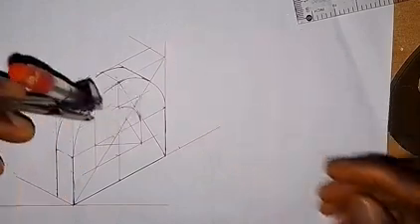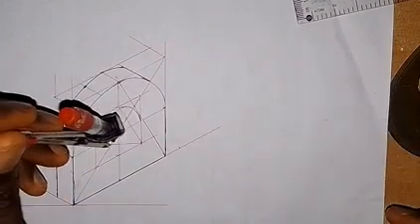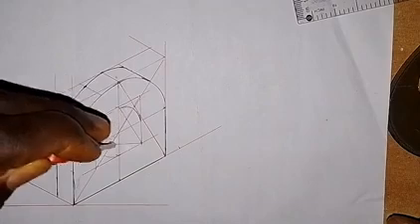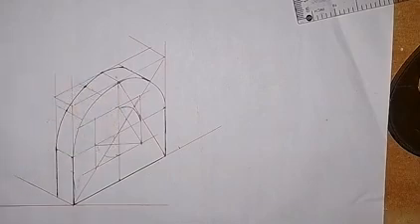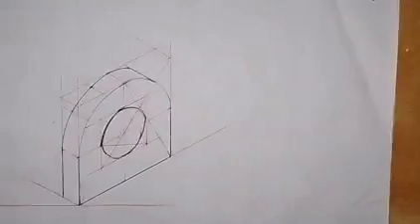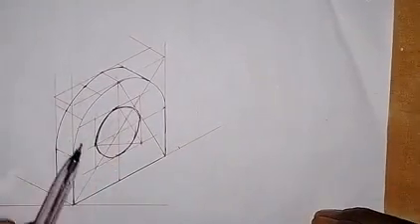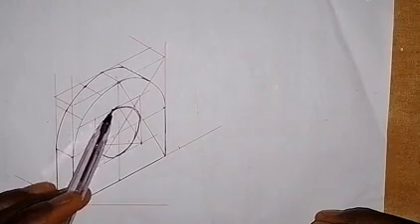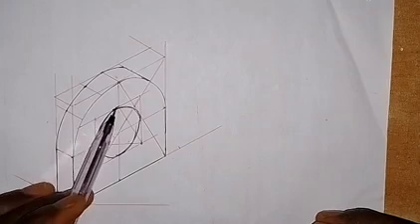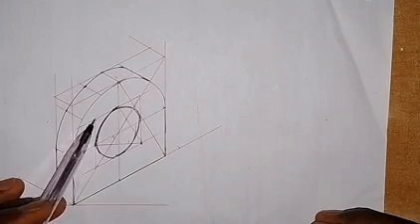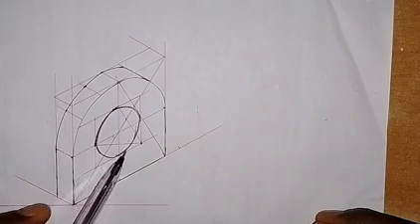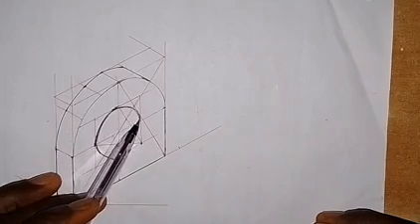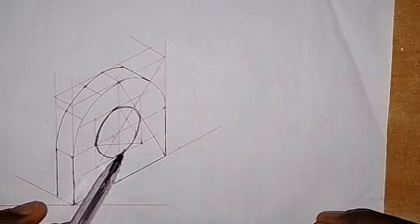Okay, so we draw this arc, and then we put the compass at this point here. From this point, we draw an arc. Alright, so this is the isometric circle. All you have to do is make use of these points. Extend your compass to this point and draw this arc from here to here, and then use this point, extend to this point here and draw this arc from here to here, and then we make use of this point and extend the compass here, draw this arc, put it at this point and draw this arc.